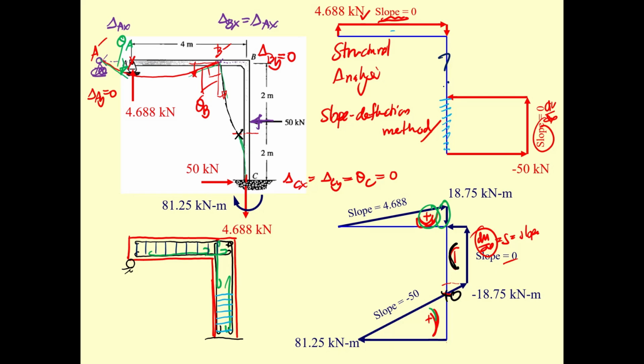The reinforced concrete design requires a minimum, even though there is no shear, you have to put minimum spacing for the stirrup. So for this one, the spacing may be the largest. Okay, so that's going to be the scale of the steel reinforcement.